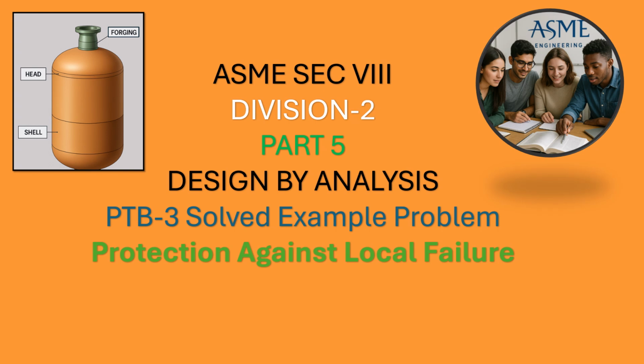To summarize, elastic analysis confirmed that hydrostatic stress remained below 4S, satisfying the code requirement. Elastic plastic analysis showed that equivalent plastic strain plus cold forming strain is far below the limiting strain. Together, these methods demonstrate that the pressure vessel is adequately protected against local failure. This exercise shows how ASME Part 5 checks extend beyond plastic collapse and address ductile capacity under multi-axial stresses.